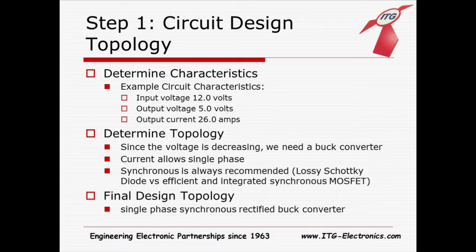Since the current is 26 amps, we can achieve that with a single phase, a single inductor. So we're only going to need a single phase for this. But if you had double this, roughly say 50 amps or 100 amps, you could use a 2 or 4 phase buck converter. It's just going to scale up that way, roughly how many inductors you're going to need to manage the desired current.